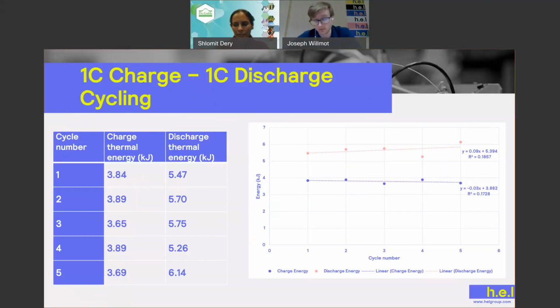What we also did was change the discharging rate and the charging rate. We changed the charging rate to 0.5C, so we're charging at 8 amps, and then we changed the discharge rate to 5C, so we're now drawing 80 amps out from this pouch cell. That's quite significant. We're really stressing the cell to get the discharge going as quickly as we safely can, to see how well it will perform.